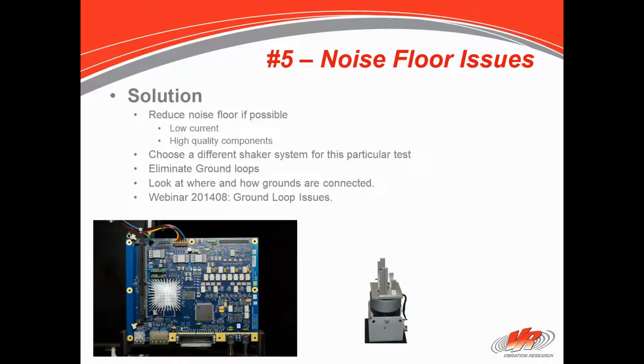The other interesting thing to point out is the computer, of course, is going to be plugged in somewhere, and the controller instrumentation is going to be plugged in somewhere. The cool thing about Ethernet connection is on the 9500 we actually have a transformer inside, so there's no common ground between the Ethernet tied to the computer and the instrument. They have to have their own grounds, which means you can actually separate them.